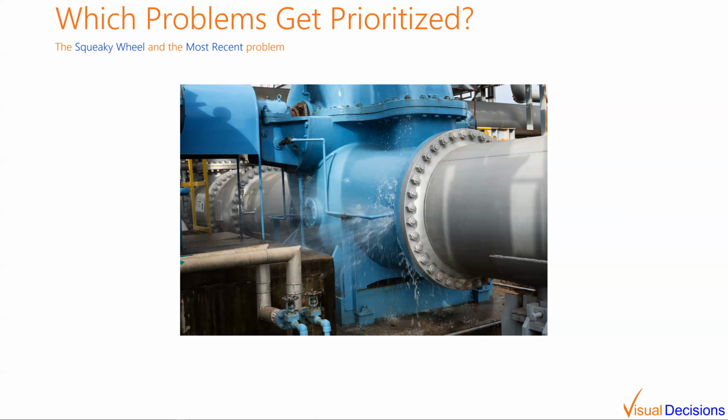And the operator, wherever they were on the line, would have to see that andon light flashing. Then they would make their way over to the filler, see that the overhead conveyor was jammed. They'd take a broomstick and they'd poke at it until the tipped over bottle cleared and things started flowing again. And when I talked to the operator about how often that happened and whether something should be done about it, he said, well, that's just the way it works.